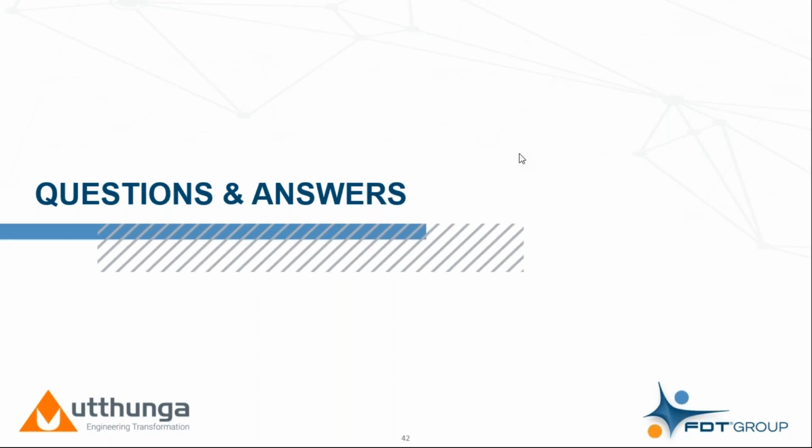Next question is, do the device DTMs define which information model is added for the device in the OPC UA server? To answer this question, it is not the device, because FDT wants to ensure that all the devices, whatever communication protocol or device profile they support, are treated equally. So it is the FDT OPC information model that defines what information is exposed. To say it simply, whether you are connected to a temperature sensor or an actuator, via the FDT OPC information model you will be able to receive the device identification information, the online and offline configuration of these devices, process values, device health status, and many more. So this is what the FDT OPC information model provides, but you are always free to extend this OPC information model.